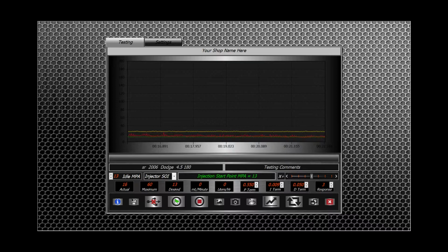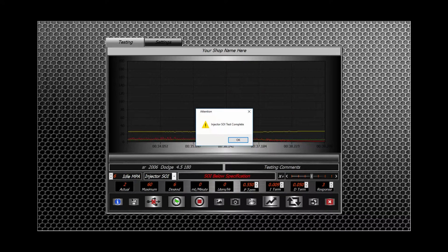The engine should be cutting off right now if these injectors were calibrated as they should be. You see the idle is getting difficult. All right, and it gets down to 6 before it dies. It shouldn't get below 14, or shouldn't be able to get below 14 without starting to run extremely rough and then the engine dying pretty soon thereafter.